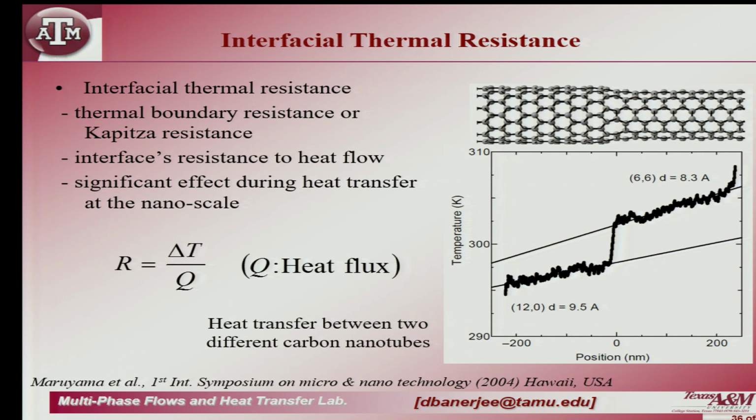We know this from solid mechanics, right, from your vibrations and damping classes, isn't it? The diameter of your cylinder determines the natural frequency of the cylinder, isn't it? So, as a result what happens is the vibration that travels along this tube, once it encounters this junction, a part of it gets reflected back, a part of it travels into the tube with a smaller diameter, and a part of that vibration gets scattered. Okay.